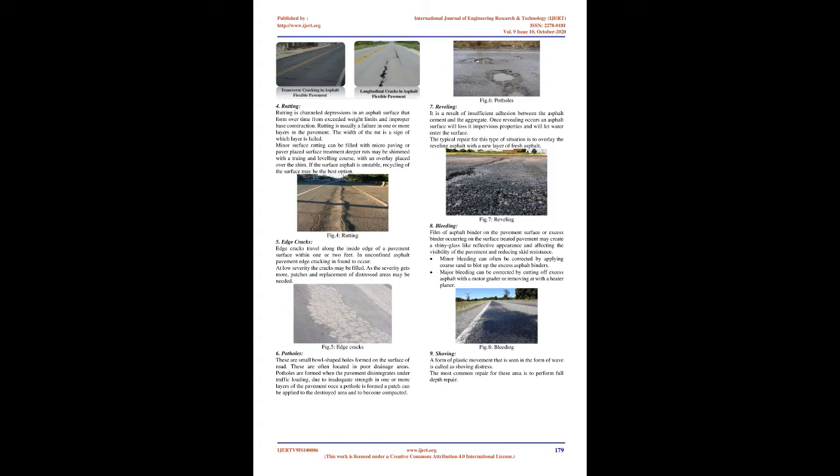3. Longitudinal cracking and transverse cracking. This distress can be considered as either a structural or an environmental distress. These are long cracks that run parallel to the center line of the roadway. The transverse cracking is formed perpendicular to the pavement center line, at approximately right angles to the center line of the roadway.